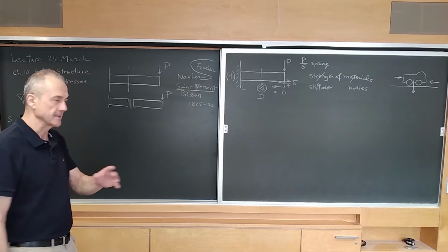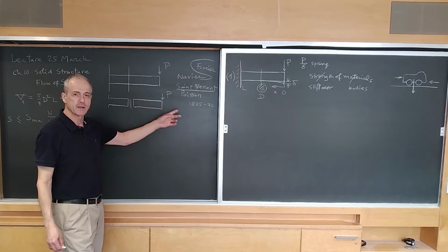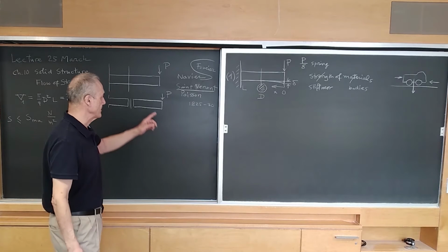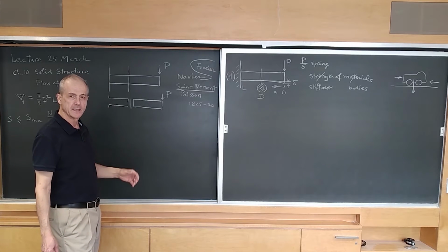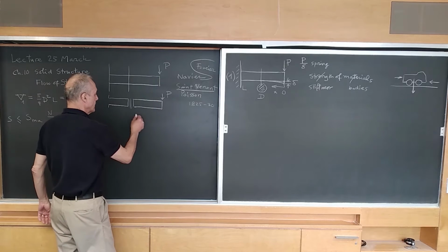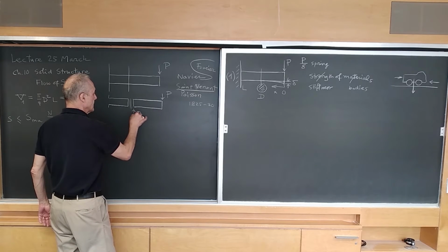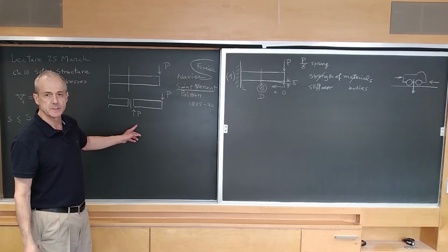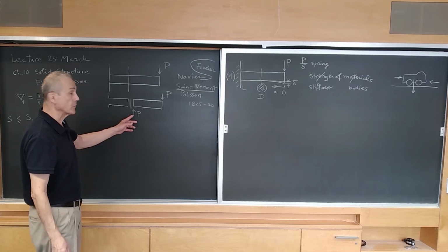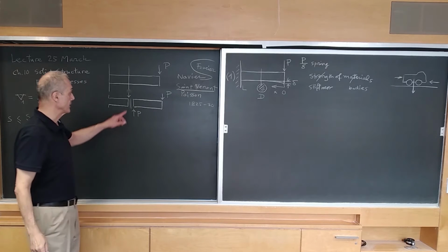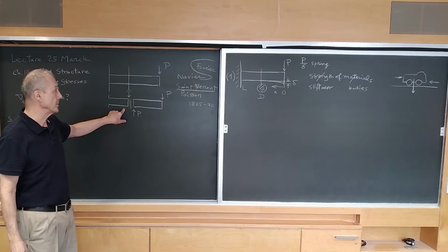But wait a second, this piece that is to the right is not going anywhere, and that means that that piece, as imaginary as the stump, is subjected to forces that are in equilibrium. That means that in the vertical direction, in the cut, there must be a shear force of size P. The shear force, of course, has to be acting on the mating face of the stump.